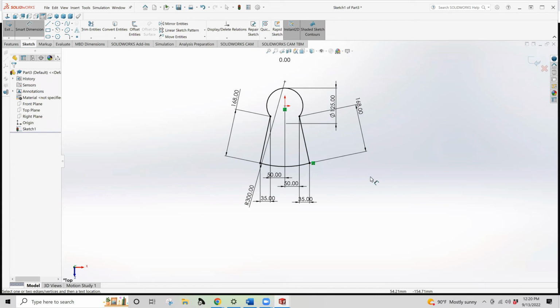So that's how to get control over seemingly complicated geometry like that. It's really just a couple arcs and a couple lines. It's just a matter of learning how to specify enough information that it knows where the starting and ending points are. And once all of this is established, there are a couple of these dimensions that aren't strictly necessary for maintaining full definition, but you can leave them there for the purposes of the process.